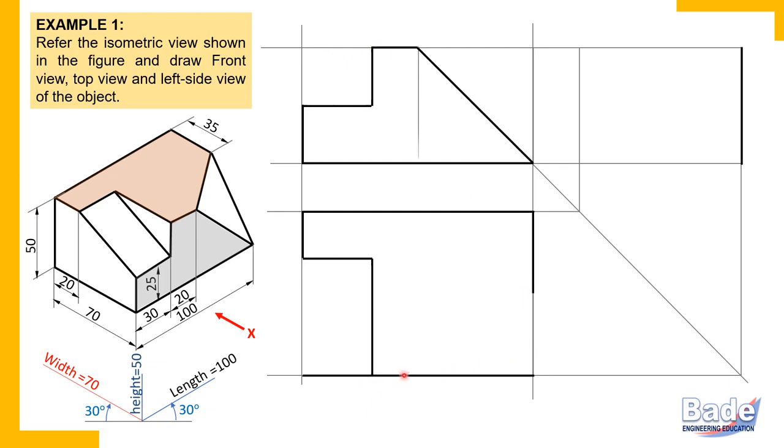20 millimeters you may measure independently here, or you may draw projector. For smaller details, I prefer independent measurement. I avoid drawing projectors for smaller details. Okay, so this is that length 20 millimeters. So this end we got it.